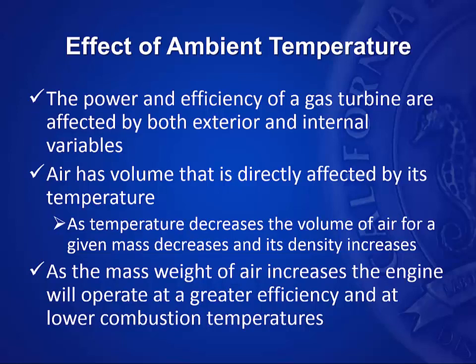This very dense air is going into a constant area, right? The intake of this engine is constant. And so if we increase the density of the air coming on the intake, that will dramatically increase the mass air flow rate. Now let's compare that we're running this turbine down at Palm Springs and it's 120, 125.